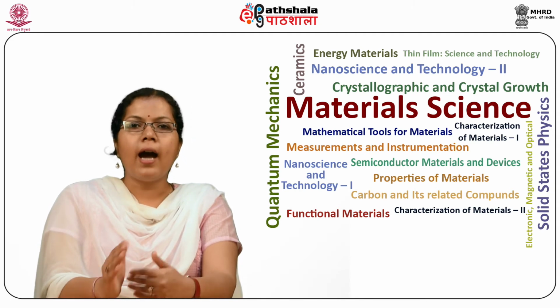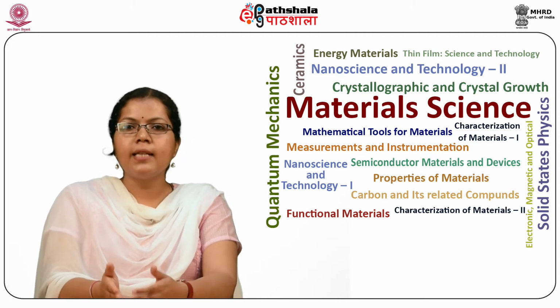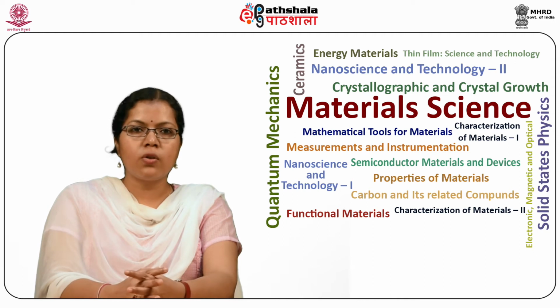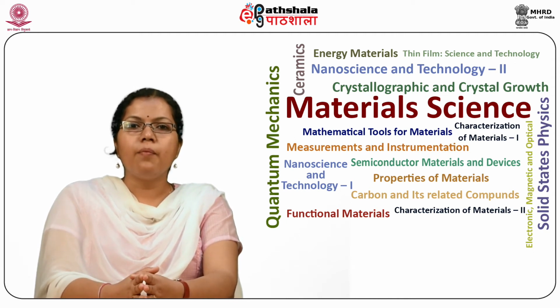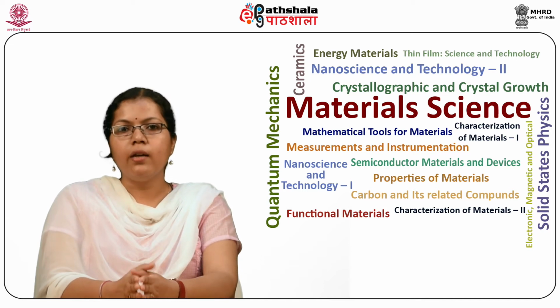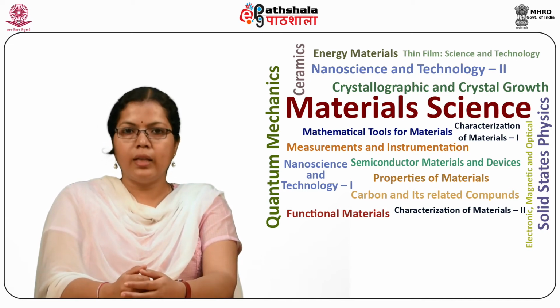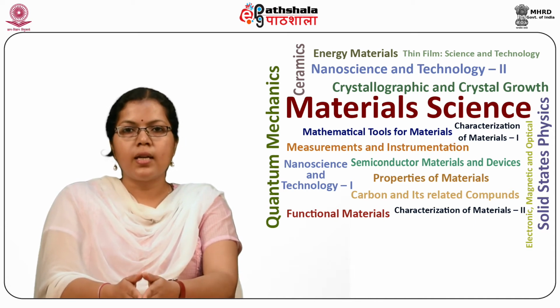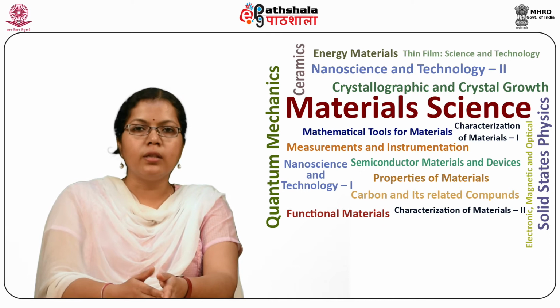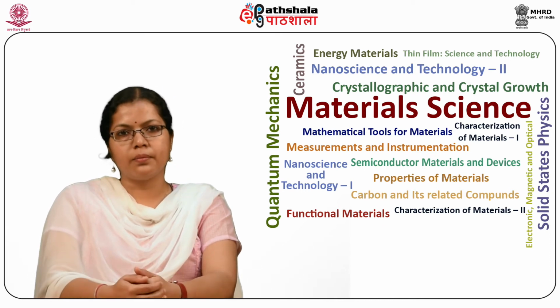Second, they have high sensitivity, as high as 20 amperes per lumen when compared with 100 microamperes per lumen for a photoelectric cell. Third, depending upon the cathode material, the spectral response can vary from 100 nanometers to 1000 nanometers.